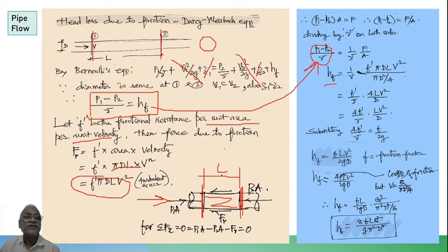I have considered circular pipe with a diameter d. So F dash by gamma, pi cancels off, one of the d goes, so 1 d remains in the denominator, lv squared, right. So 4 F dash by gamma lv squared by d, that is what remains.